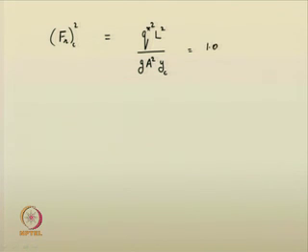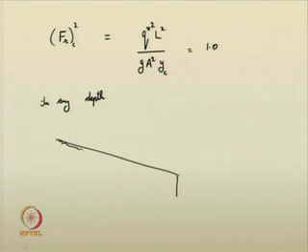So, the Froude number at critical flow in the same type of rectangular channels, we can now suggest that Q squared by g A squared yc, where yc is the critical depth, should be equal to 1. Now, for any depth along the sloping rectangular channel, here lateral inflow of water is there.